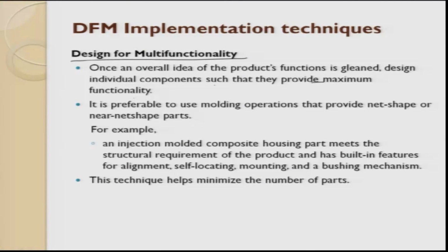The moment you have understood that all these sub-assemblies can cater to all the needs of the customer, then I start linking these sub-assemblies to make each sub-assembly or part multifunctional. So, it is preferred to use mold operations, which is why polymer comes in a big way, or composite comes in a big way.